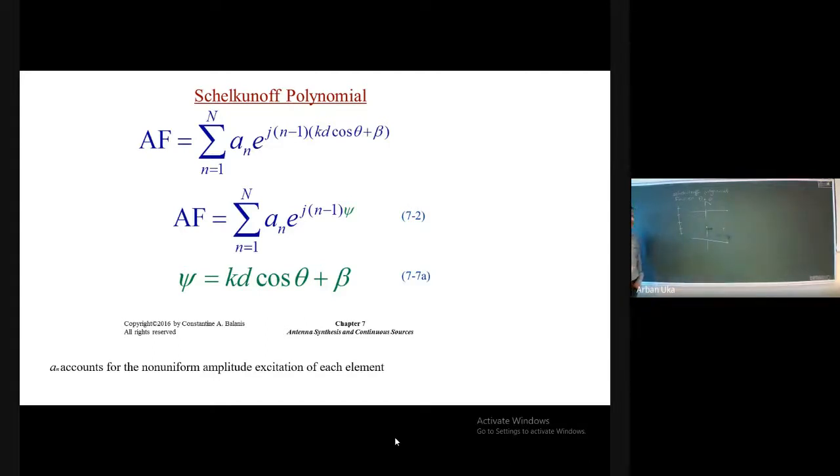We're not native speakers, but whenever we have this design of the antennas, we know that we start from the first one, so this is the array, and we go up to n, and then we give the constraints of how the nulls should be. So we have to figure out what this dependency on theta will be, and then we also have another important parameter, which is the letter psi.